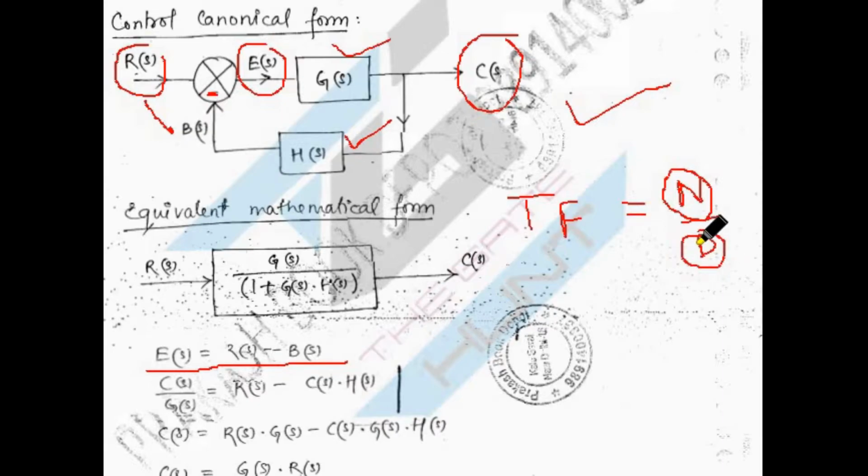So if you are finding a transfer function for any system, you have to calculate it in the s plane only. So output divided by input, and the most important statement is that you have to consider all initial conditions equal to 0. If you follow this condition, then you are able to find the transfer function.